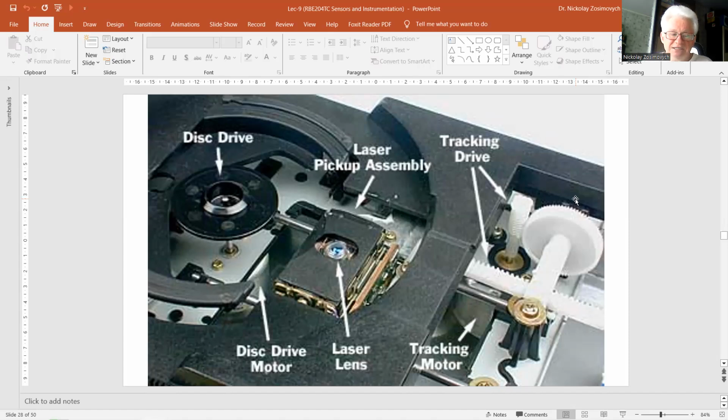Systems in which the sensor faces the source, or direct mode, have the widest range, up to 35 meters. Indirect mode systems have a smaller range because only part of the scattered light will return to the sensor. With special reflectors or retroreflectors, the maximum range is about 10 meters, when only the reflection of the object itself is viewed, at a distance range of several meters.